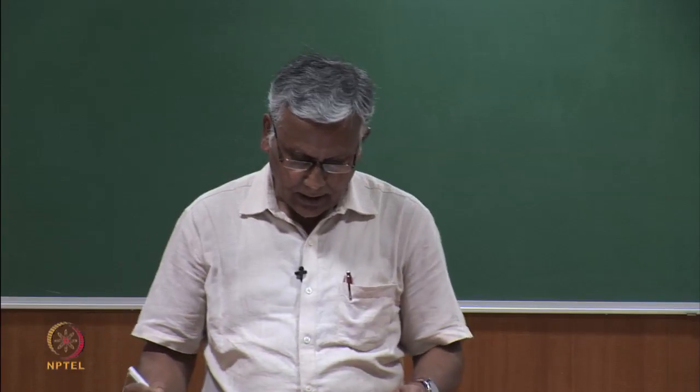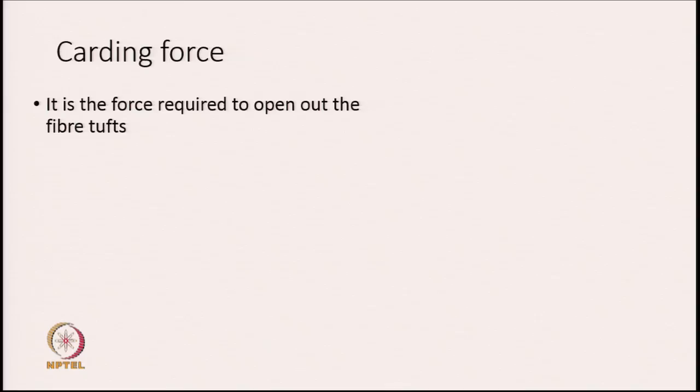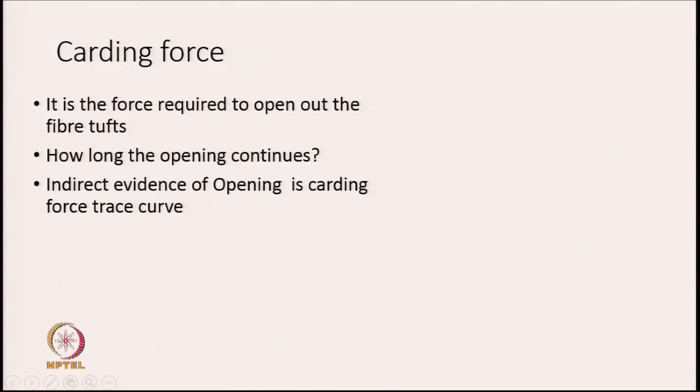We will discuss analysis of flat action today. The carding force gives us some indication about the opening action. The force is required to open the fiber tufts. The question that comes to mind is how long the opening continues. Indirect evidence of the opening is given by the carding force stress curve.